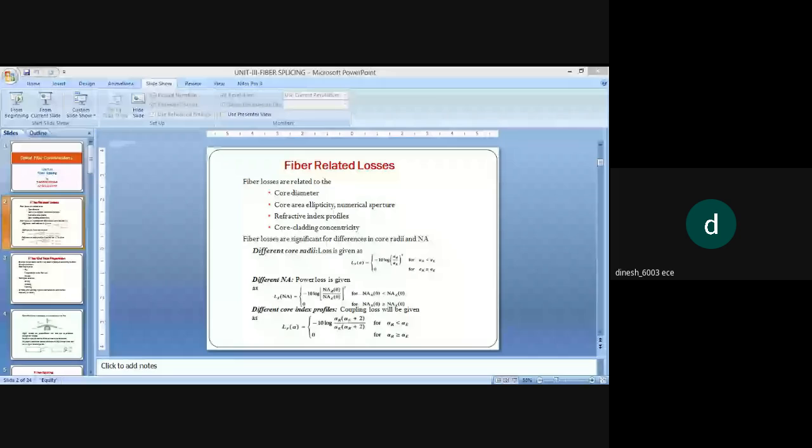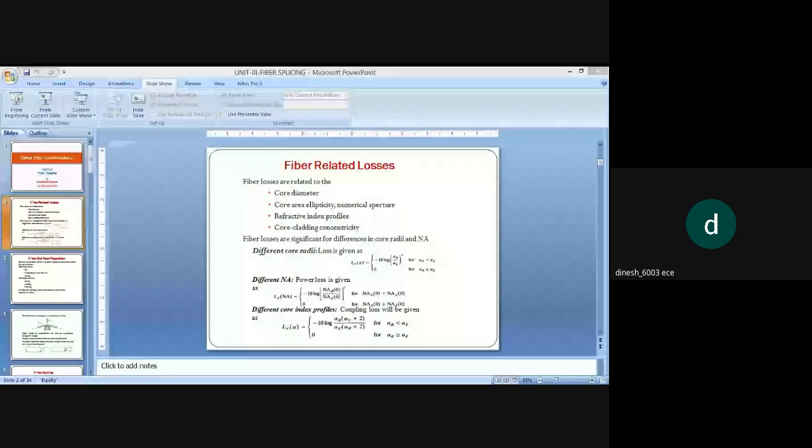So the fiber preparation quality is that for splicing it is necessary to ensure that no damage occurs to the core being cut. So any damage to the unprotected glass, micro cracks, can cause the fiber to break during handling, splicing or storage. So the entire optical fiber cable should be properly prepared for splicing.